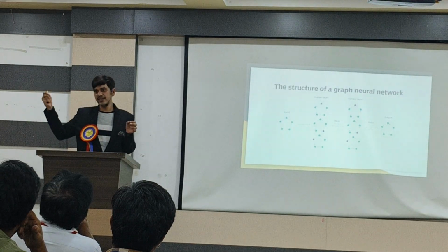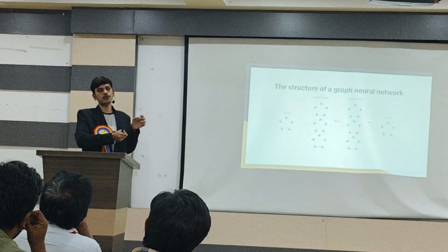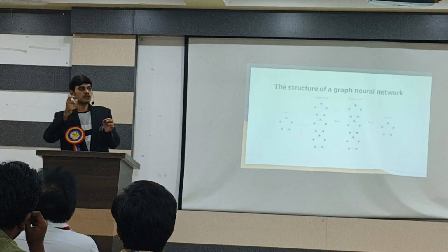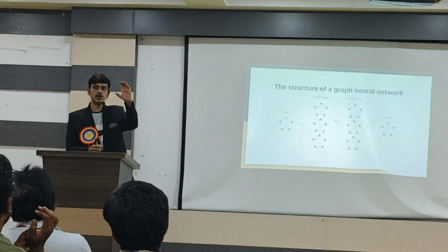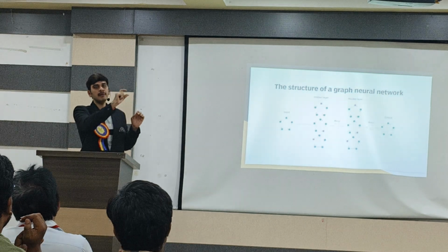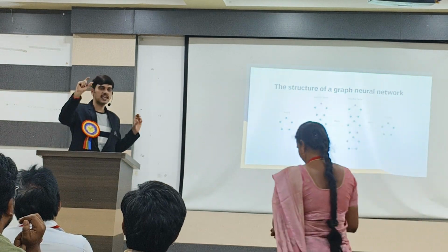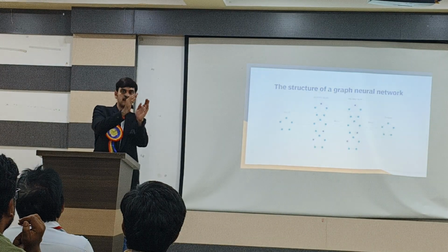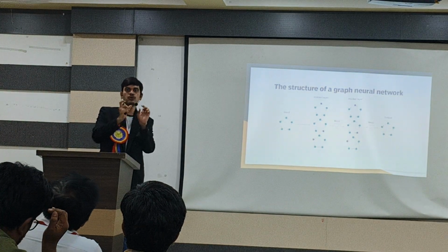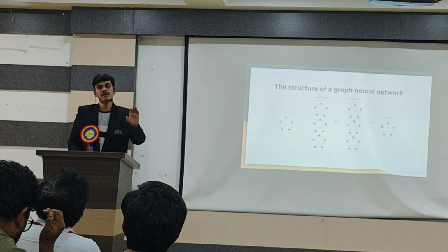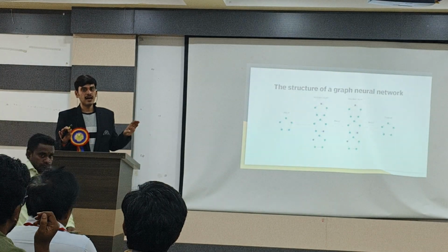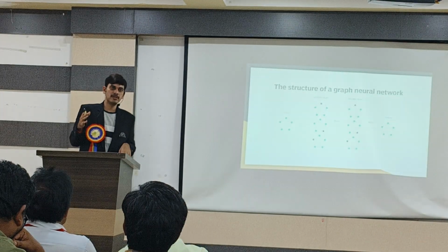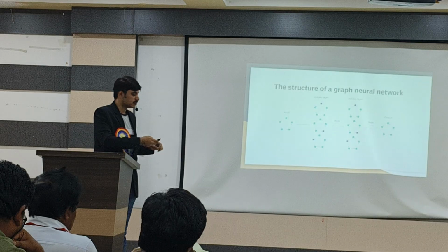So, for example, if you take the floor plan as a feedback input to the synthesis, the synthesis engineer can know where to place the macros. If the proper macro is placed at a particular location, the timing will actually be better. If there are two macros that are far apart, based on the floor plan feedback, those two macros will be kept near, so that the timing will be met for them. The system is a highly complicated design, so these macros will be in the thousands or lakhs. I will just give you an example.